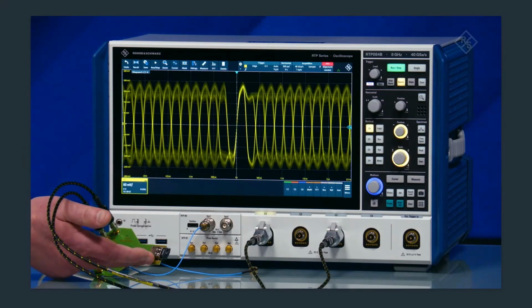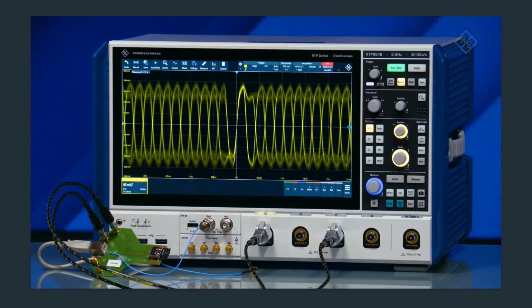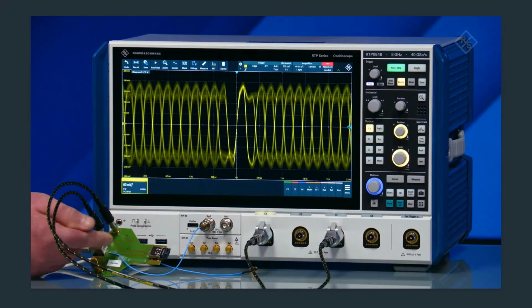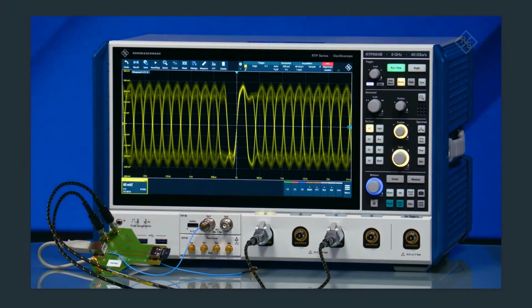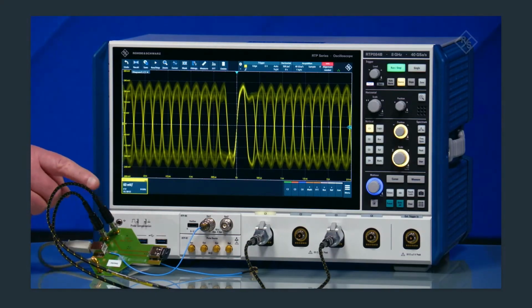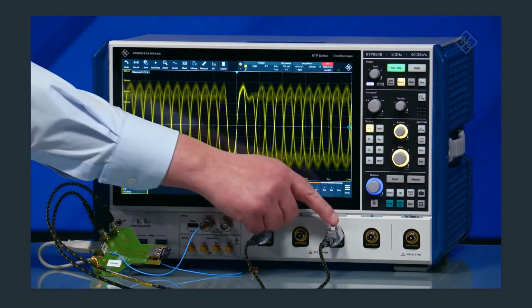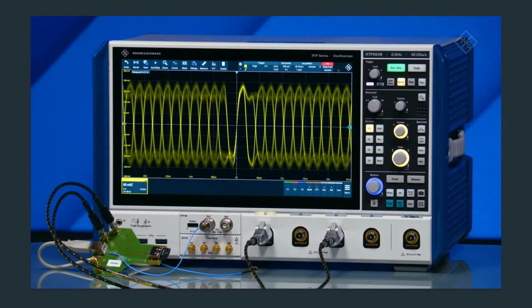The memory stick is connected to the test fixture, and then we are able to measure the TX line of the USB stick itself. The connection between the oscilloscope and the test fixture is differential. From the TX plus line, we are connecting one cable to oscilloscope channel 1, and from the TX minus line, we are connecting one cable to oscilloscope channel 3.